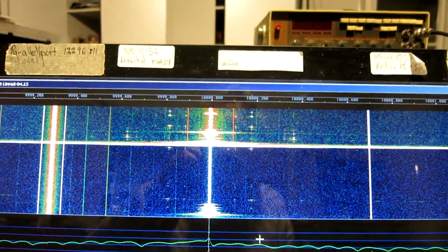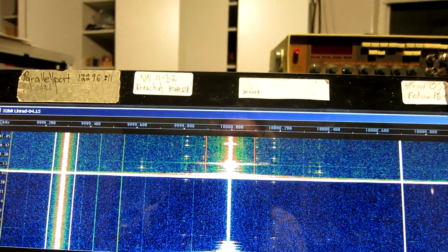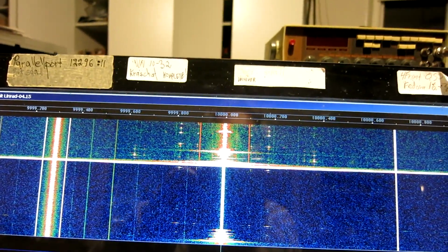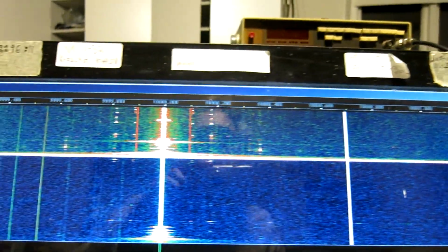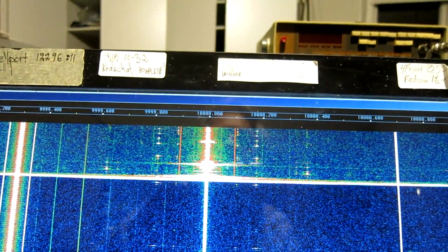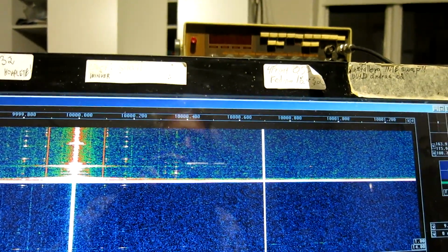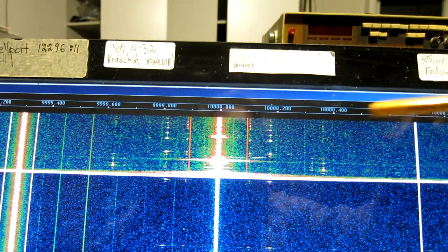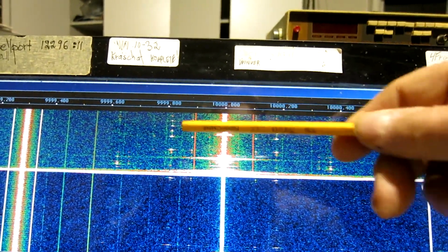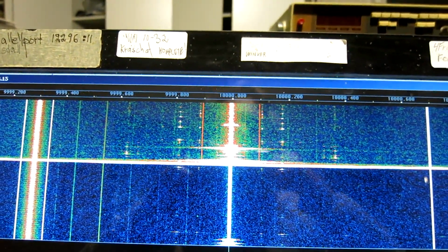And here is the good crystal, number 163, at 3 dB attenuator setting. And you can see the wide noise floor has gone up. And I think that's caused by the crystal. And we have now these phenomena. These are oscillations in the crystal.